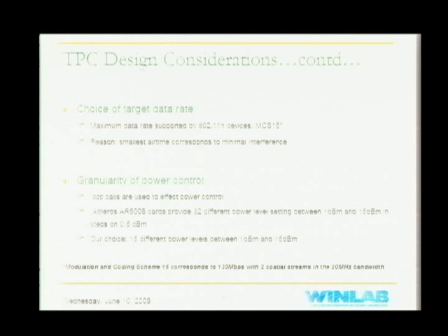I think if you lower your power, you can get spatial reuse at some point. That's right, but you can't take up all the time you want and not affect another station. The spatial reuse depends on both the amount of time as well as the power that you transmit at. So the average power received, you cannot change that. But what he's pointing out is that within the cells, when you operate at the highest target data rate, you create the least amount of traffic interference within a given cell. That part we agree on, if everybody is close. But if there are other stations around, it's not optimal.